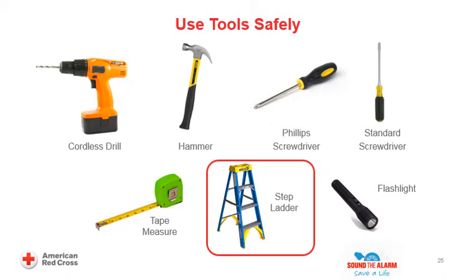It is the documenter's responsibility to hold the ladder step stool while the smoke alarm installer steps up and climbs only as high as necessary to reach the installation point. Follow guidance printed on the ladder step stool or in the instruction booklet. It is the documenter's responsibility to hold the ladder step stool and pass materials up to the smoke alarm installer. Caution: never stand on the highest step of a ladder or pail shelf. Never walk under an open ladder. Do not climb the back of a step ladder.